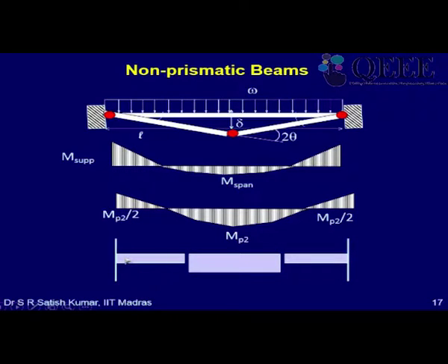So I am not providing a tapered type of beam, but I am providing a stepped type of beam. I can choose 2 different smaller beam sections. Let's say this may come out as ISMB 200 and this may come out as ISMB 300. So I will get economy in the beam design on one side, and at the same time, since I have to now connect only a smaller beam to the support, I'll also get economy in the connection design.